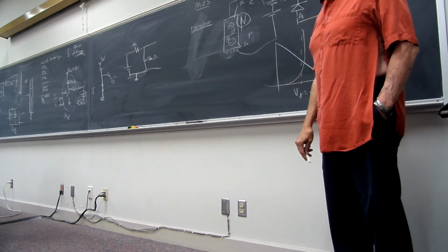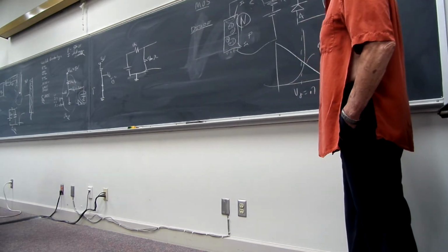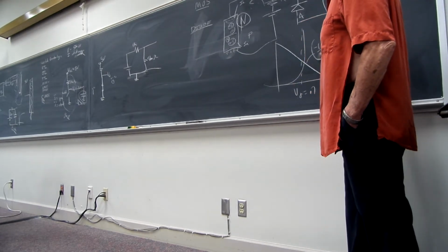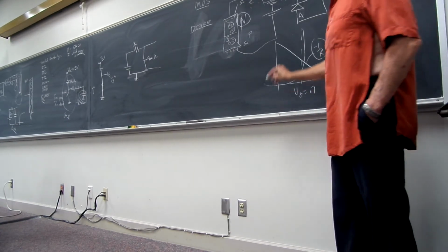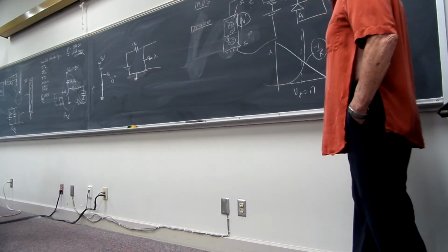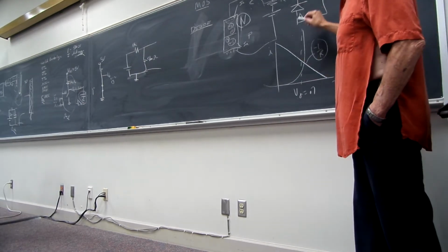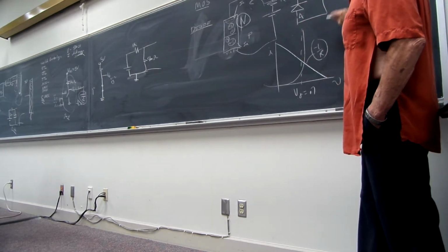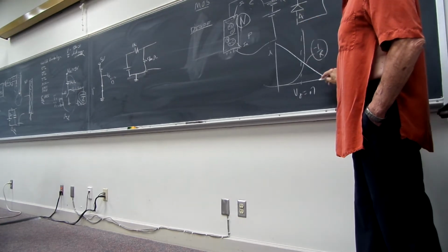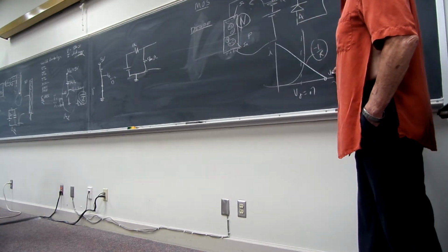You superimpose on that the circuit looking out that way there. This is -1 over the resistor value for the slope of that line, if this is current and this is voltage here. What's the maximum voltage looking across the diode there? What's the maximum voltage we could ever see? It would be our VCC.